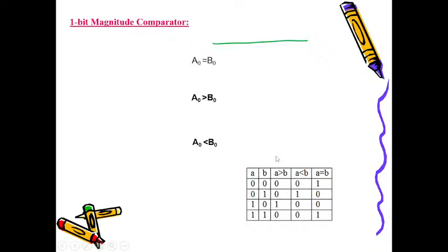You know the block diagram. A magnitude comparator, put it in a block, and I'm going to come out with a circuit. So that is your block. How many inputs? Always two inputs, A and B. How many bits are A and B? One bit. A is going to be one bit, that bit could be either 0 or 1.